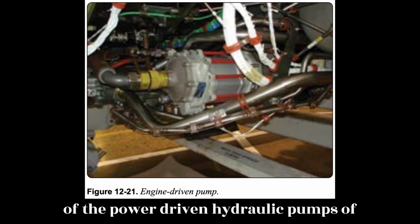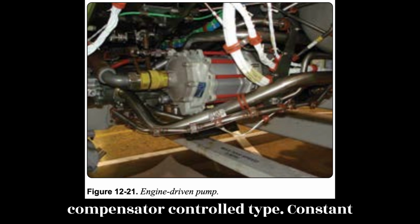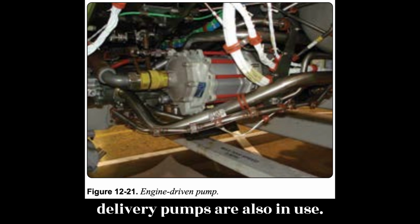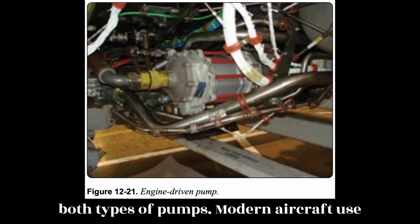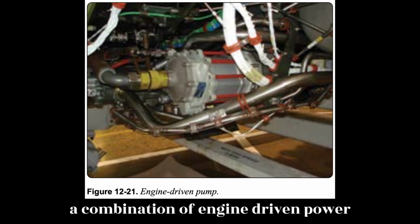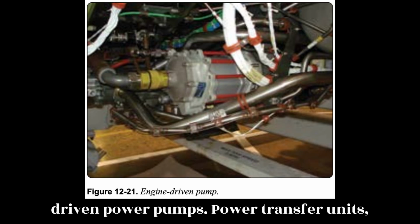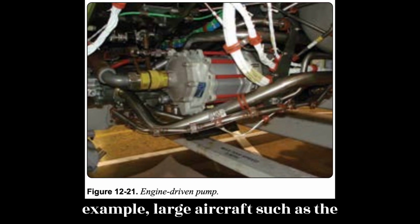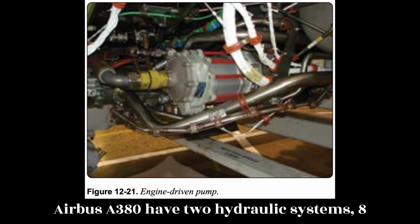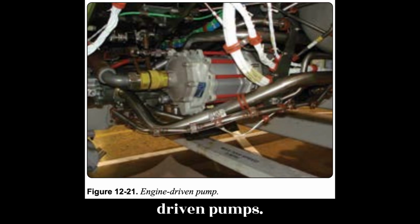Many of the power-driven hydraulic pumps of current aircraft are of variable delivery, compensator-controlled type. Constant delivery pumps are also in use. Principles of operation are the same for both types of pumps. Modern aircraft use a combination of engine-driven power pumps, electrical-driven power pumps, air-driven power pumps, power transfer units, PTU, and pumps driven by RAT. For example, large aircraft, such as the Airbus A380, have 2 hydraulic systems, 8 engine-driven pumps, and 3 electrical-driven pumps.